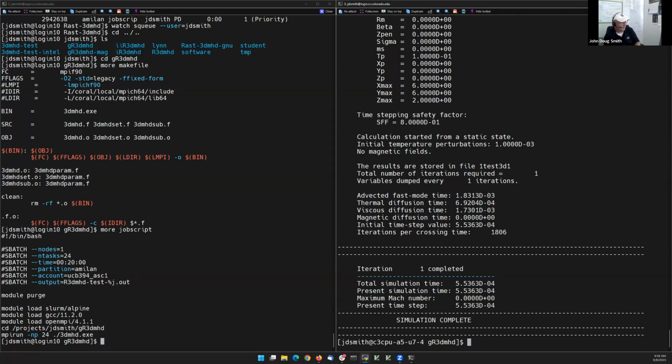The optimizations, how you lay this out on your cluster, how often you dump time steps, being able to, having run this enough beforehand to be able to go, oh, he is going to want, this simulation calls for 1,200 time steps. What does that look like running on my cluster? How should I lay this out? How many processes should I give it?